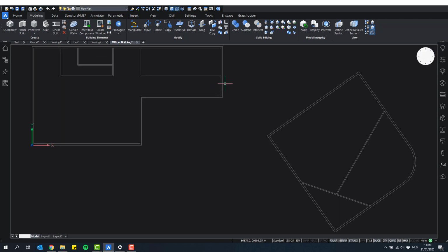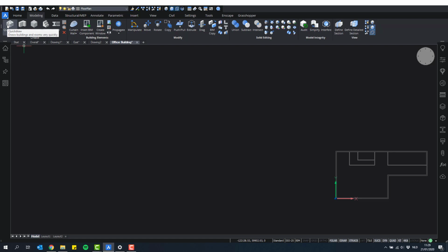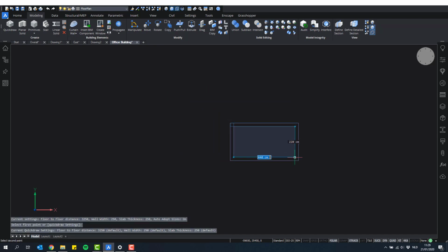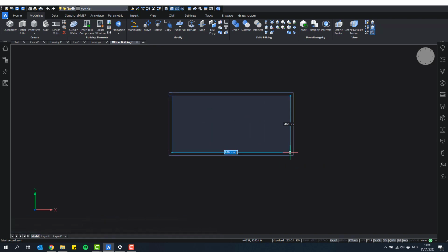So QuickDraw is basically, I'll maybe just quickly explain it apart from the layout here. If I open QuickDraw, you will see a special cursor appear, and it basically shows you the room that you're going to create and the walls around it. So if I just click somewhere, if I now left click, you will see that there's actually 4 walls and this simple room in between.